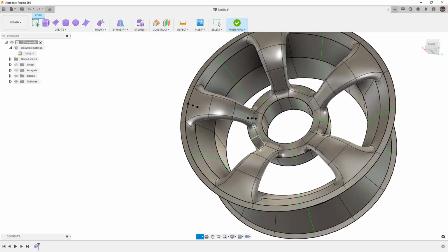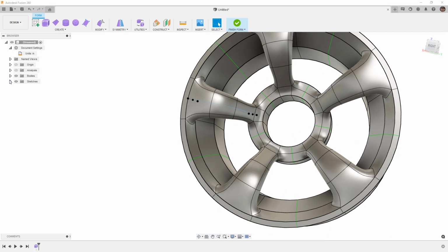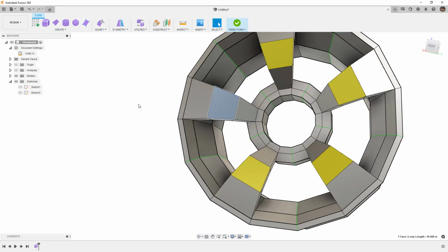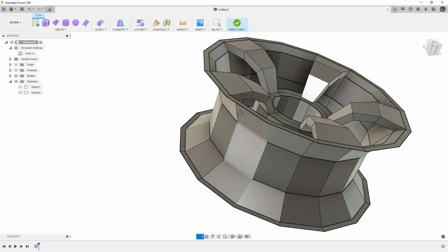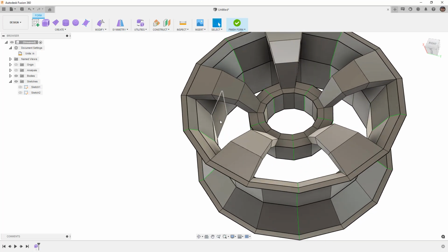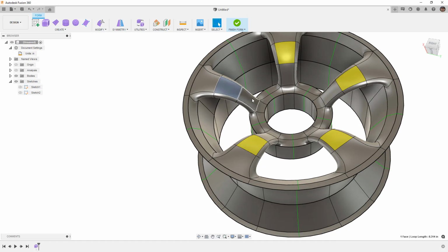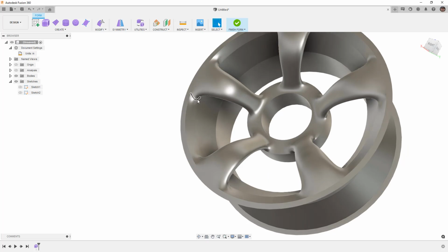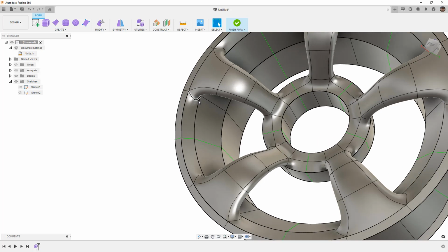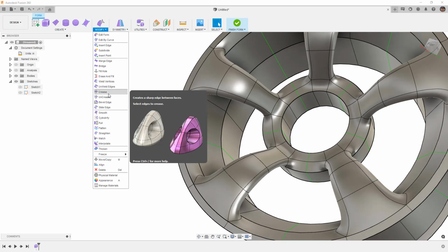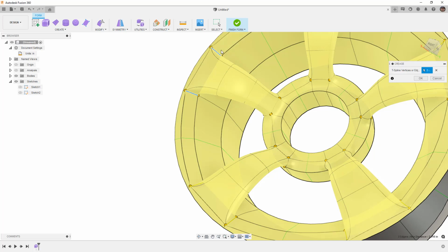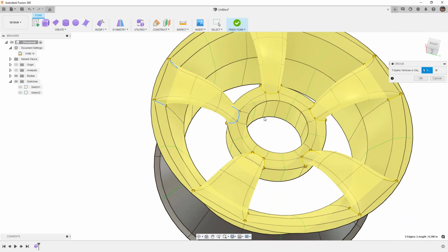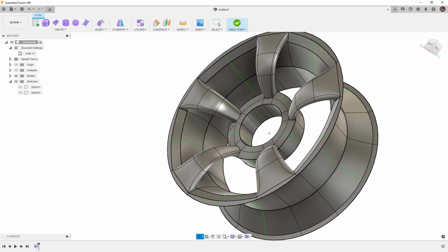That was pretty quick to make that shape. This is a good time for us to go into box display mode, which again is Alt and 1 on the keyboard. You can also go to display mode here and take a look at the results. Everything looks pretty good so far. When we go back to smooth display mode, you can see that these shapes are very gradual, very smooth, and the way that it blends into the rest of the design is probably not what we were expecting to see. But if we go to Modify and Crease, and we crease these edges where it enters the design, and make sure that the back one stays creased, we'll say okay. And now you can see that we've got a little bit different result.